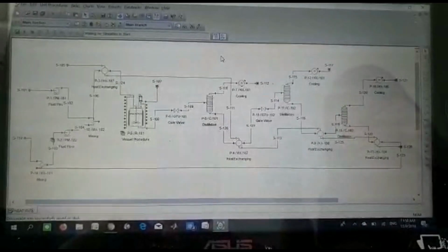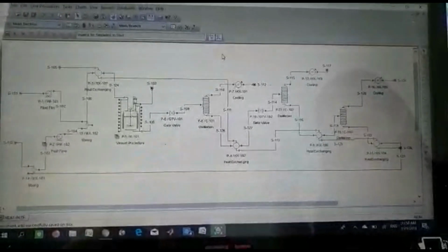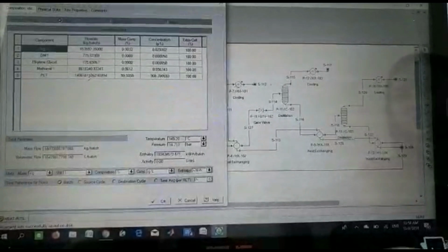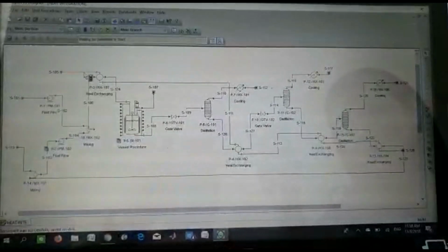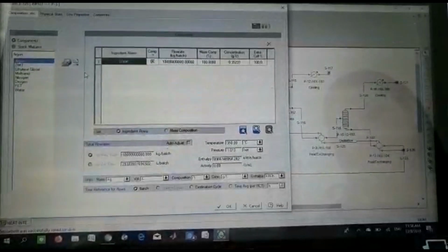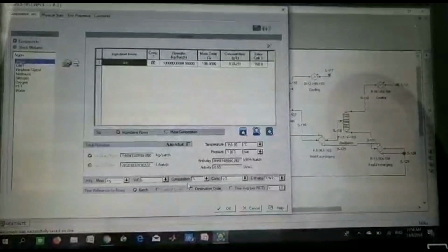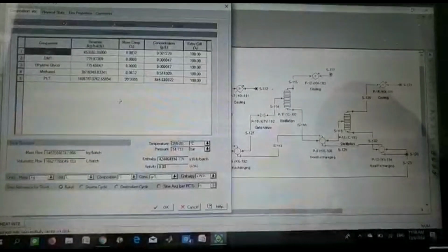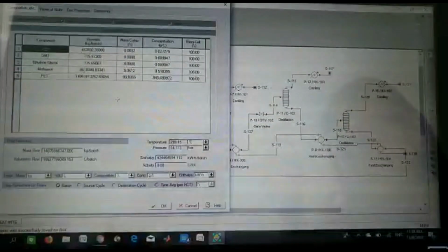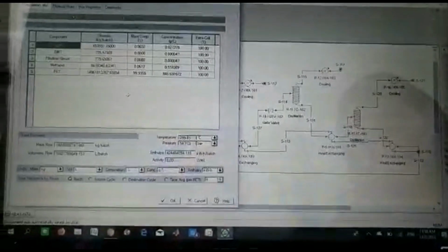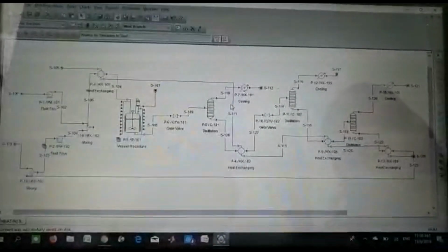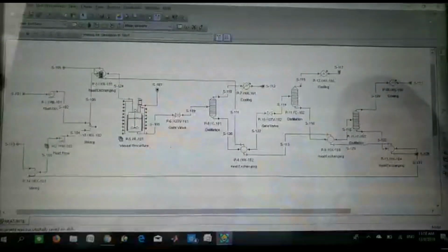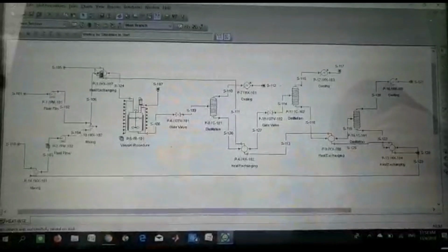Heat exchanging is used instead of electric heating and heating units. At P3, S106 acts as the cold water and S105 acts as the hot water, which is at 350 degrees Celsius. And the desired product is 299.85 degrees Celsius. So this means that we can use heat exchanging in this process. The trial and error method is applied to S105 in order to get the desired product.